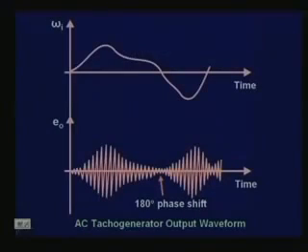So if you have a DC tacho generator and the speed changes like this, then from the AC tacho generator you have what is known as a modulated waveform. Again you have an AC, but the amplitude of this is exactly like the LVDT. The only thing is that in the LVDT the EMF looked exactly like this, but it was proportional to the position, the motion of the core. Here it is proportional to the speed of the shaft. That is the only difference.